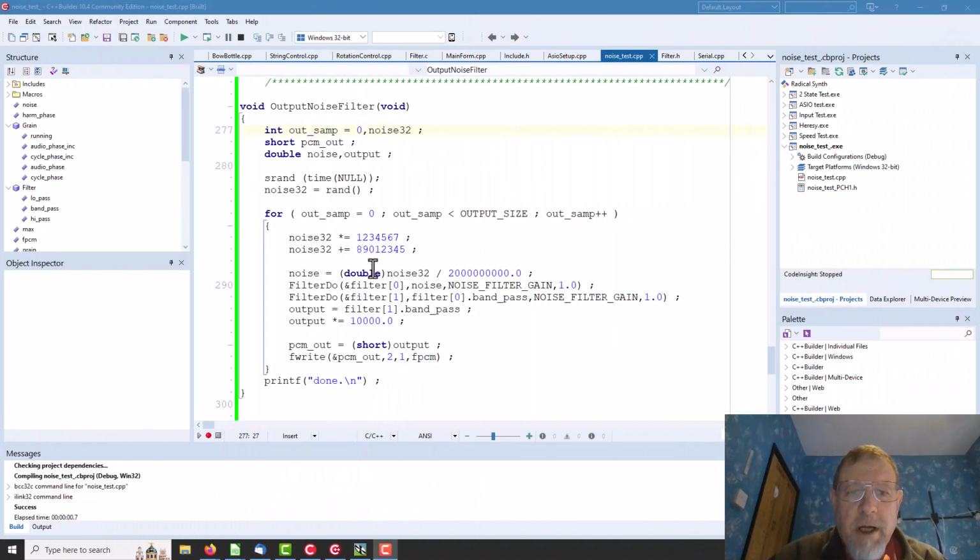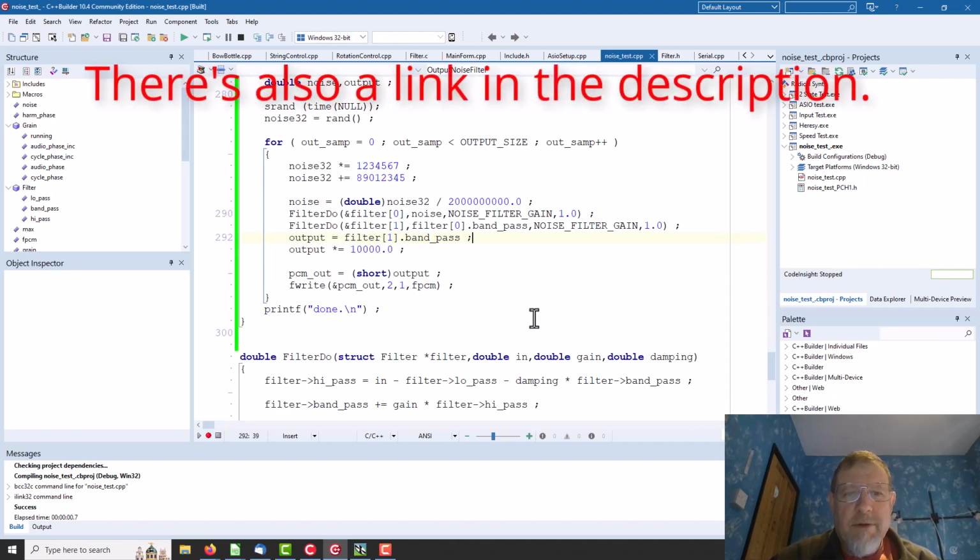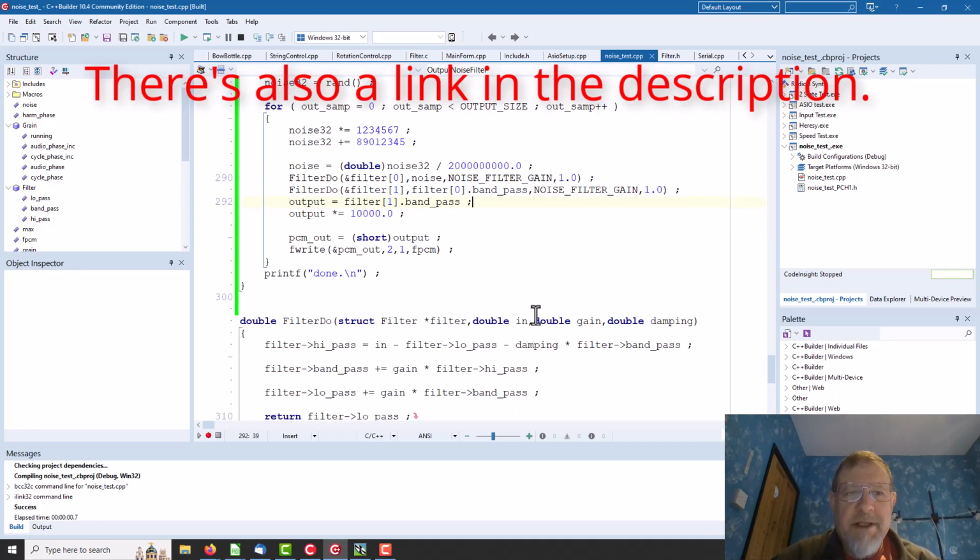Right. Okay, so we don't want to use our horrible sounding white noise, we want to filter it. We want it to peak at about 1 kilohertz and then fall off either side. So I thought we'd just try, for first approximation, our good old state variable filter of the type we used in the Mean Green. So if you look through the synthesis tutorials, I go through how it works in some detail.